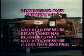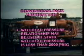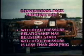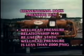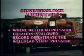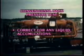If the wellhead shut-in pressure is less than 2,000 psig, the IOCC allows a deliverability equation based on wellhead pressures. If the wellhead pressures relationship is to be used, the wellhead static pressure must be recorded or estimated. Corrections to recorded pressures must be made if liquid has accumulated in the wellbore.